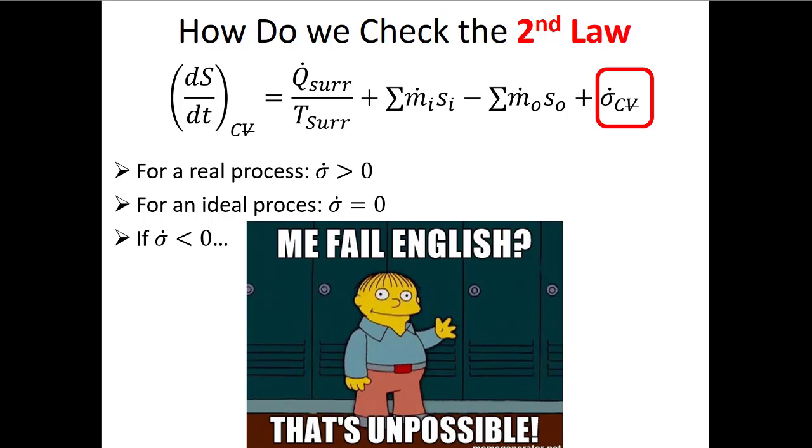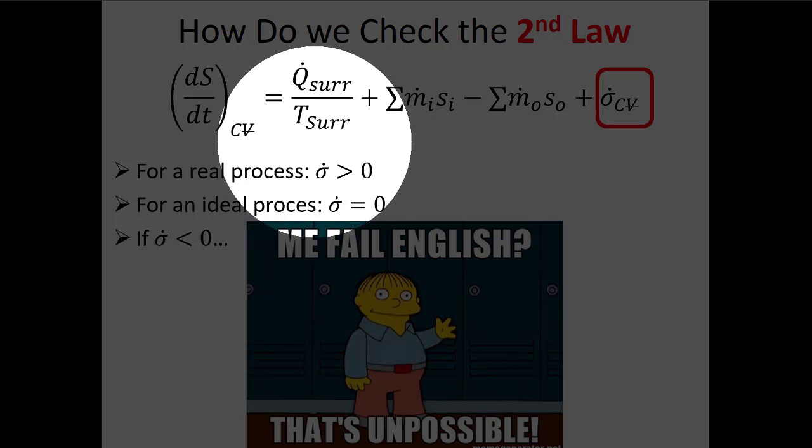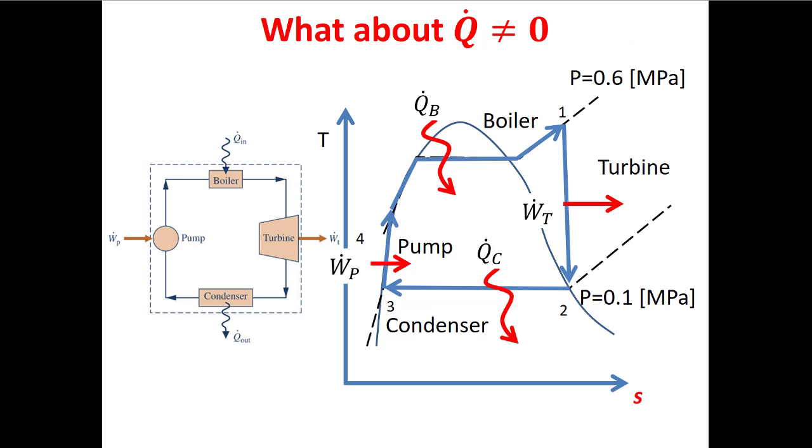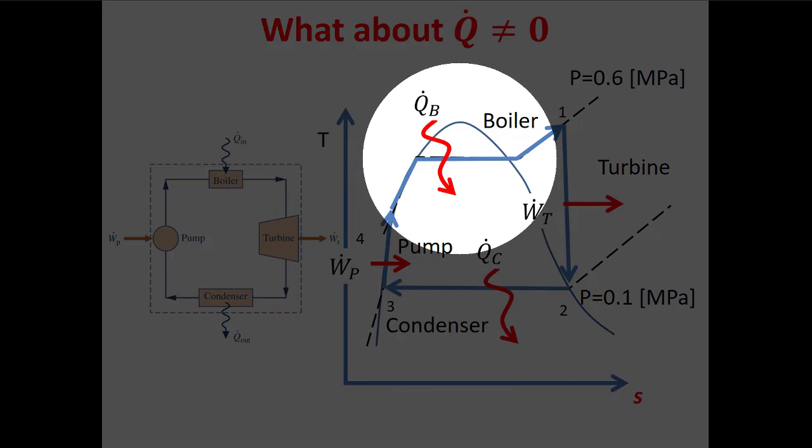Then you've got to pick the right temperature, and we'll talk about how we don't pick the temperature inside our control volume. Ideally, we pick the temperature on the boundary, but failing that, we'll take the temperature of the surroundings, the temperature outside the control volume. But you might also notice here that this is a single temperature. It's not a temperature difference. Anytime you see that, the hair on the back of your neck should stand up, and you should think, oh, this is not a temperature difference, so it matters if I pick an absolute temperature or a relative temperature. Anytime you have a case like this, you're supposed to pick the absolute temperature, a temperature scale where zero is absolute zero. So Kelvin or Rankine.